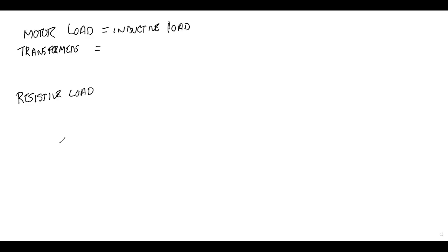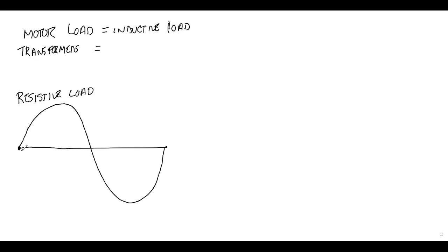Yeah. Okay. All right, resistive loads, like lights, stoves that have that element heater or whatnot. Those are the kinds of loads that we like on our system. Because when I'm producing voltage and then the amperage demand on the circuit, that's the characteristics of a resistive load. It's perfect. My voltage that I'm putting out, which is the top line, and the amperage that's needed to feed whatever I'm feeding, they're right in phase.